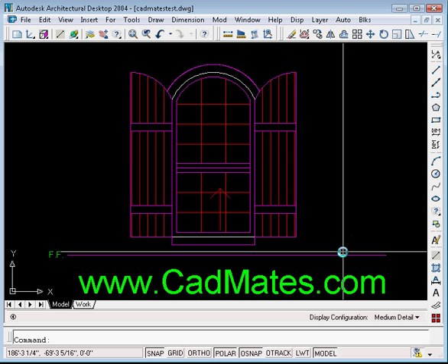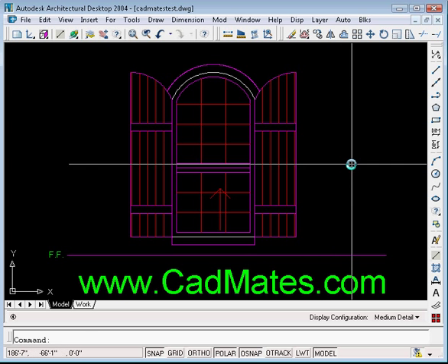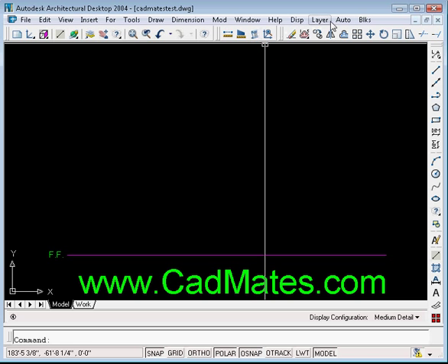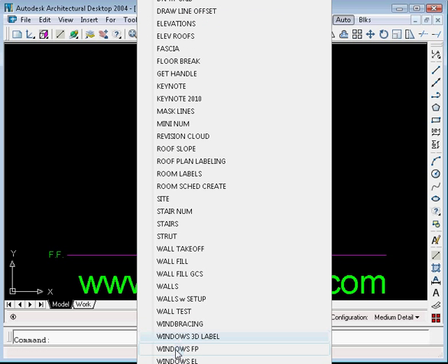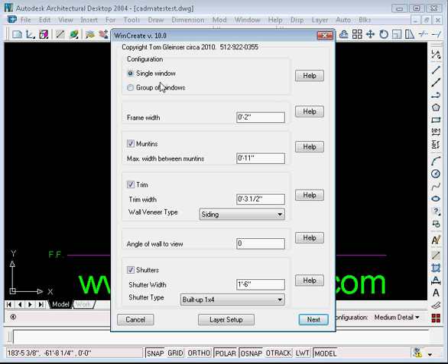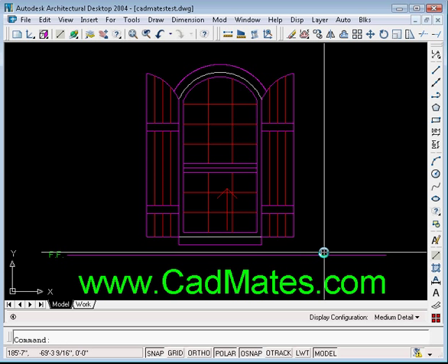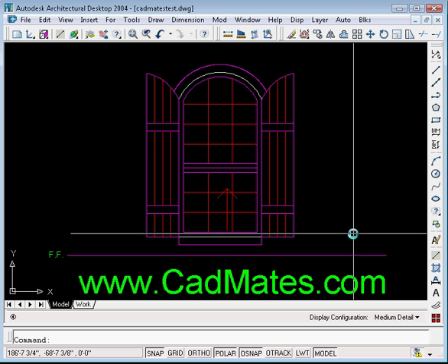and there your window draws. If you don't like it, if the shutters look a little too wide, for instance, let's erase that, start the program over again, and all of the values will be the same as you left them. They'll default back, but let's make it a 13-inch wide shutter. Of course, when you're using built-up 1x4s, it'll round off to the nearest 3.5 inches. And we'll draw that one again. There's a nice cleaner looking shutter, a little bit less in width.